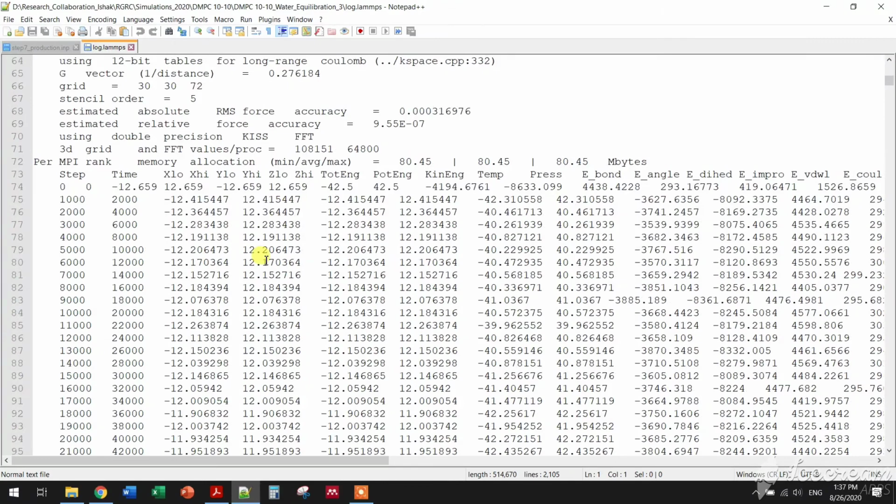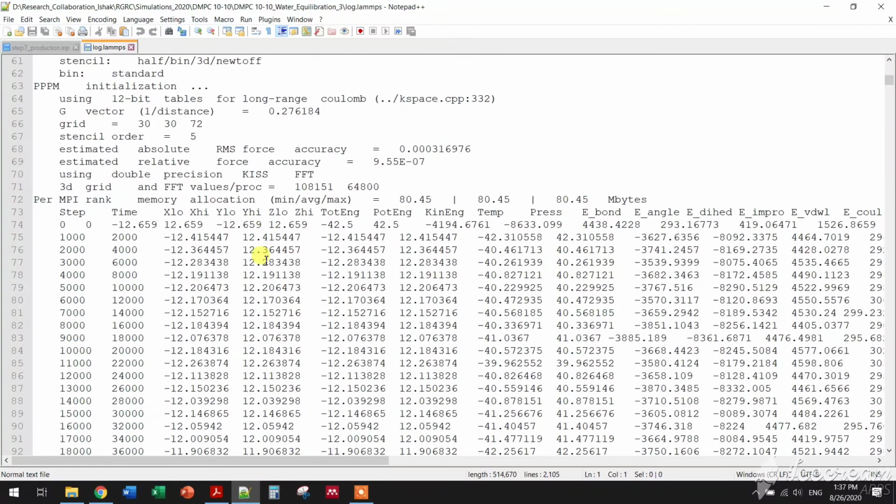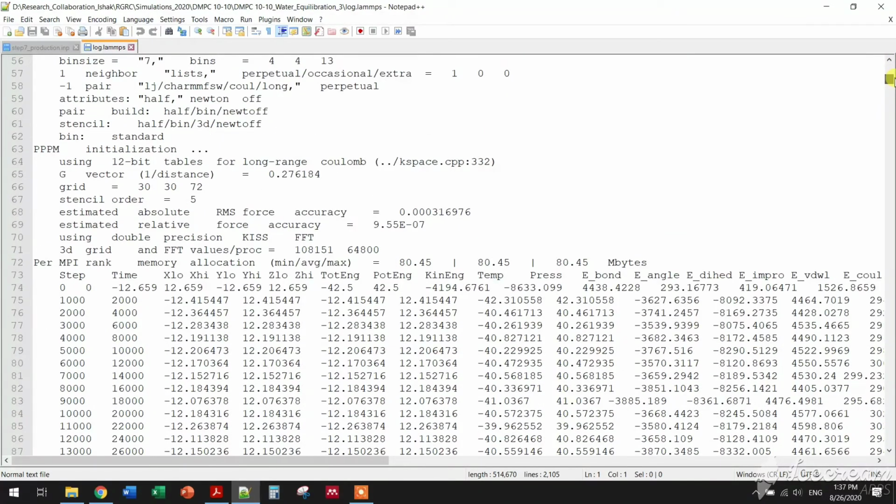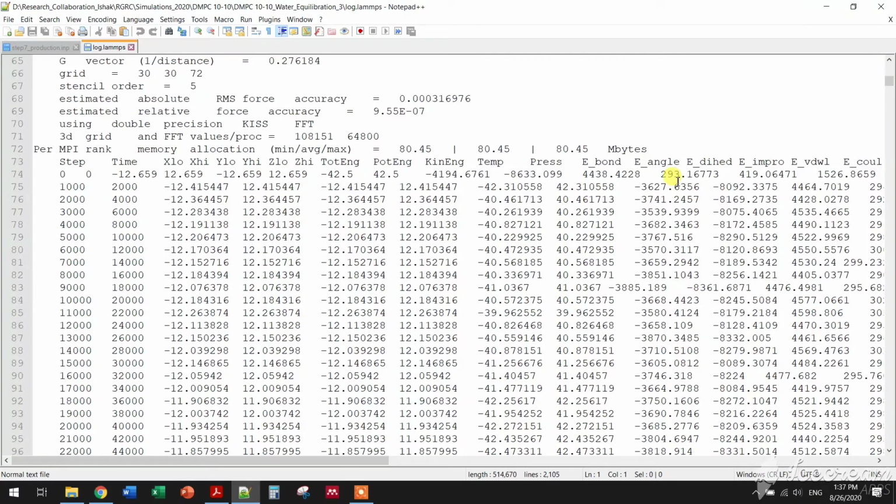And reading our file, whenever you run a LAMMPS simulation, you can actually go through your outputs. According to your input file, the log file will actually generate a pile of data, like what you are trying to see as outputs. We can plot the energy terms, we can plot the potential energy versus time to see whether our system is stable or not.